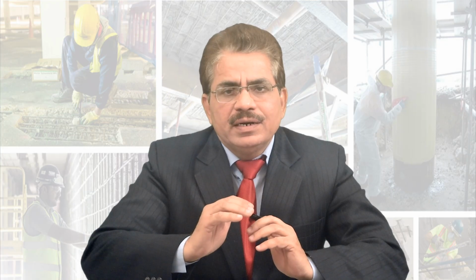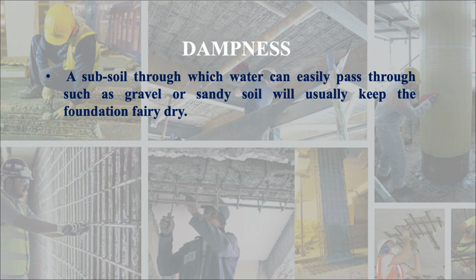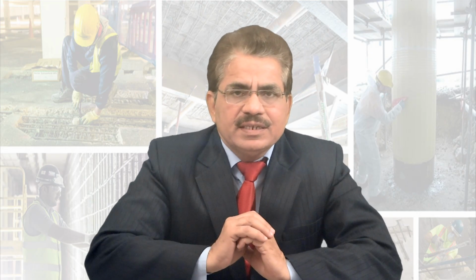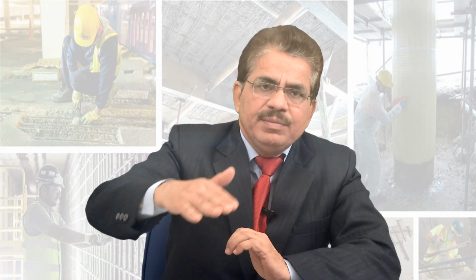So water remains there for a longer period in the soil and it causes dampness there in the structure. A subsoil through which water can easily pass through, such as gravel or sandy soil, will usually keep the foundation fairly dry. Here, if gravel or sandy soil is there in the subsoil, then as these are having large voids, so water can pass through quickly through them and the foundation will remain fairly dry. So that way that dampness of foundation problem will not be there.